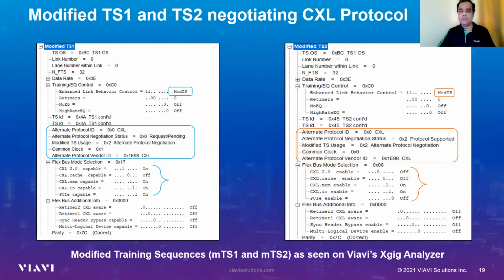But one thing to notice is one side doesn't support capability 2.0 and the other supports 2.0. So 2.0 is not enabled on this link. So we know that the link will go to L0 and will talk in 1.1 protocol version.